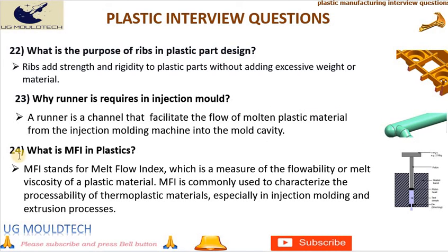Friends, next point in mold related questions is 24. What is MFI in plastics? MFI stands for Melt Flow Index, which is a measure of the flowability or melt viscosity of a plastic material. MFI is commonly used to characterize the processability of thermoplastic materials, especially in injection molding and extrusion processes.